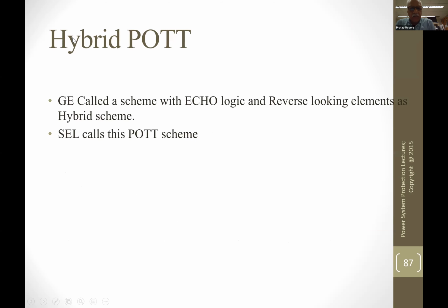Hybrid POTT scheme, they called it. GE called the scheme with the echo logic hybrid POTT with the reverse-looking elements, and that was GE's terminology. But Schweitzer calls it POTT. Like I mentioned earlier, these are all the names which they used with electromechanical relays, but the same names are used even in microprocessor relays, but with a lot more logic added into that. So in the electromechanical legacy time, when you said POTT scheme, it was a Westinghouse scheme, and if you said hybrid scheme, it was a GE scheme. But both of them are POTT schemes, and Schweitzer calls it just a POTT scheme.